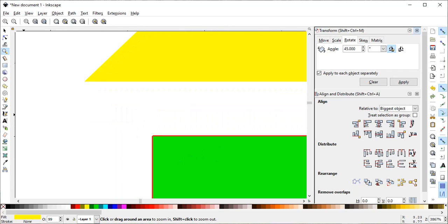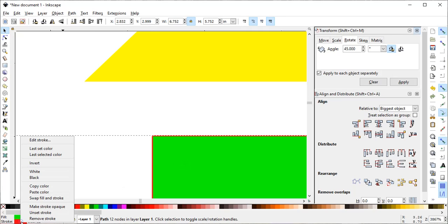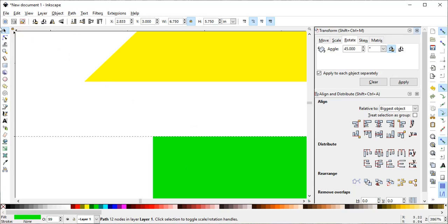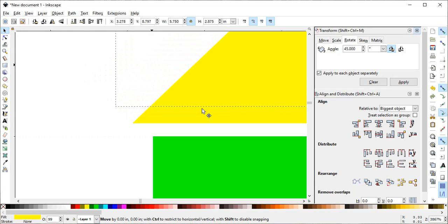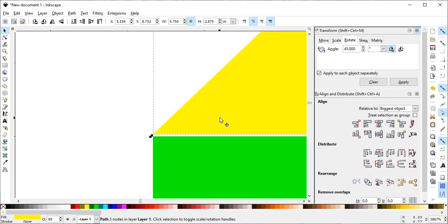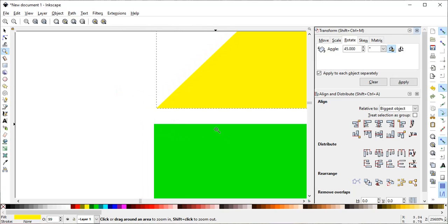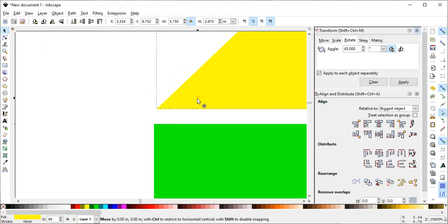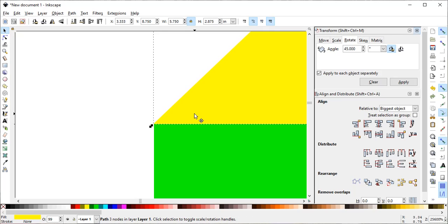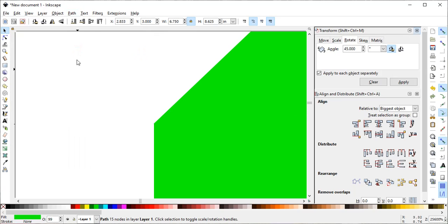We've got a stroke down here, so let's go to our select tool and let's remove that stroke. So we'll right click on this red stroke down here and remove the stroke. And have my select tool, and let's drag this down to where we're almost touching. And let's really zoom in this area here so we can see it really well. Select tool and drag this down so that it touches. And then hold the shift key and let's choose our main one, and we're going to do path and union. And so that is making our first flap.